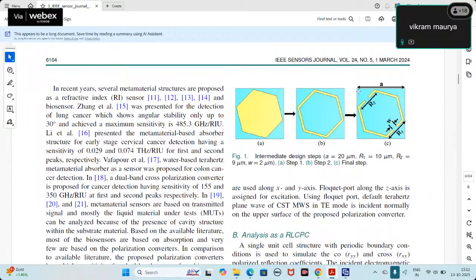And if you again make a mirror of this structure, then in the y-axis it will come here. Directly you can't make a mirror copy in the diagonal direction. First you have to choose the mirror along x, then mirror along y, then paste it here. And another way is to directly make a complete-length rectangular patch here, because in between there is no geometry. It will cover both the sides of this hexagon, and you can subtract it with the hexagonal ring.